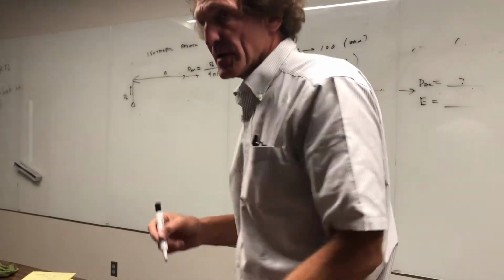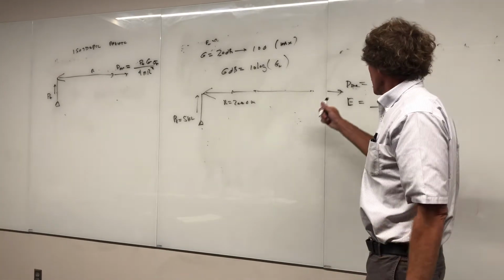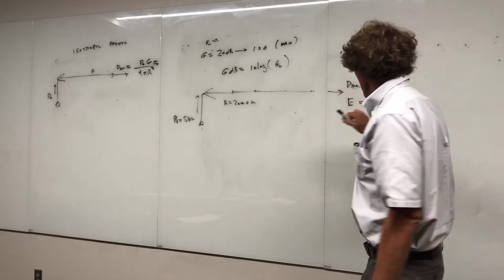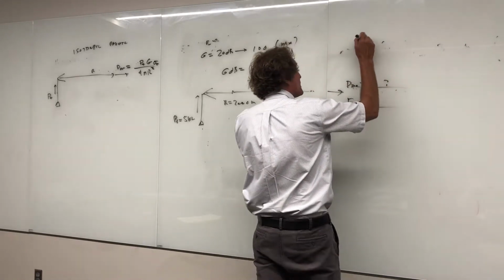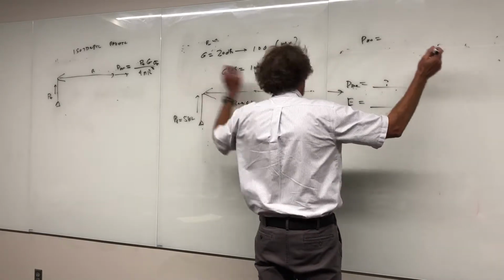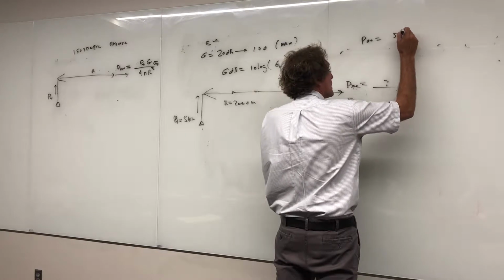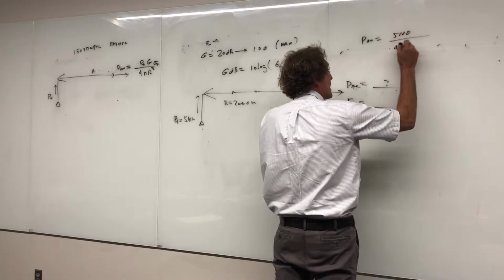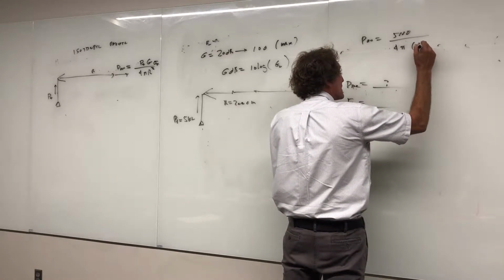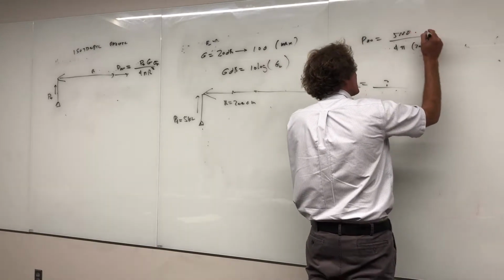Can everybody see this? Everybody comprehend what I'm saying? So for starters, I want to find the average power density here, right? How do I do that? Well, P-Av would be equal to the transmitted power, right, using that equation. Transmitted power, which is 5,000, right? Then I divide it by 4 pi. R is 2,000, so 2,000 right here. I square that. And then I multiply this whole thing by the gain.